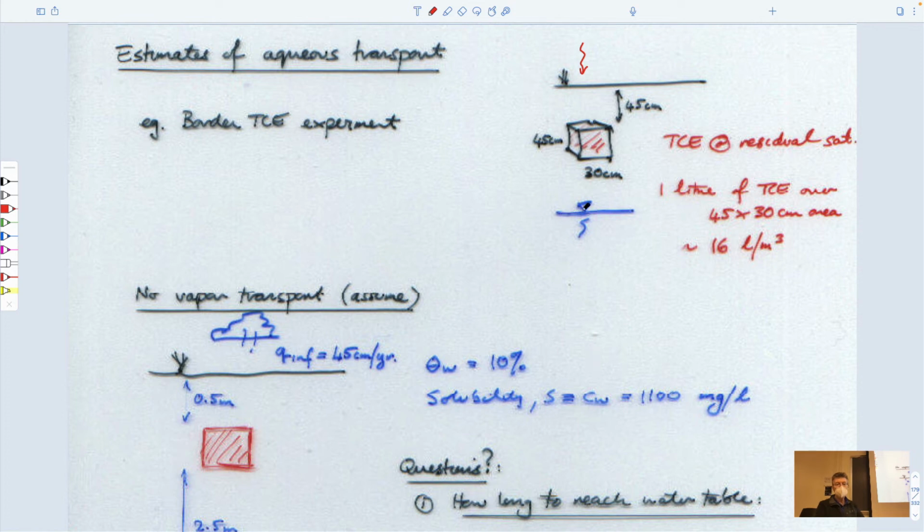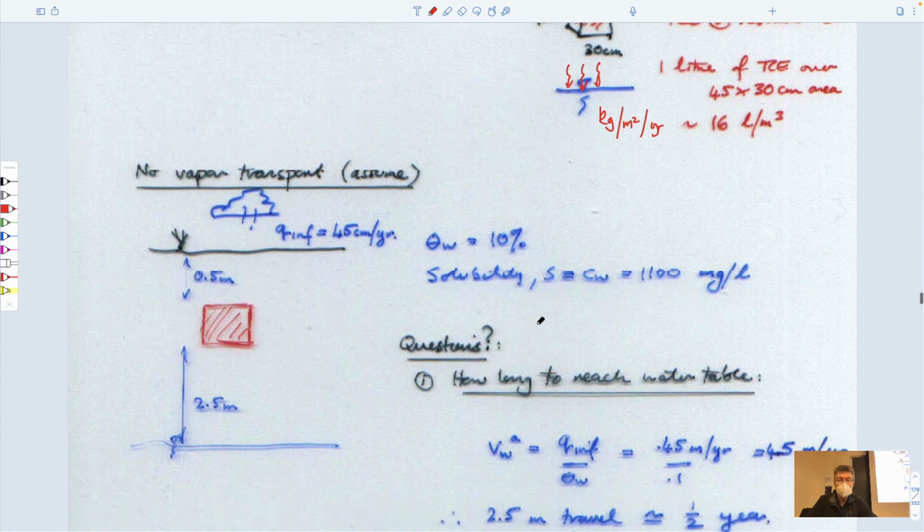And so how do we determine what the loading is that will end up onto the water table as a function of rainfall? If I can draw a cloud here. Rainfall raining on this, some infiltration on the surface, which gets carried down here, picks up dissolved components at a maximum level here, and then carries that mass down to the water table. We'd like to be able to calculate the mass in kilograms per meter squared per year, I suppose, right? How much of this dissolved mass is going to come down here? So how can we rationalize that largely on the things that we know?